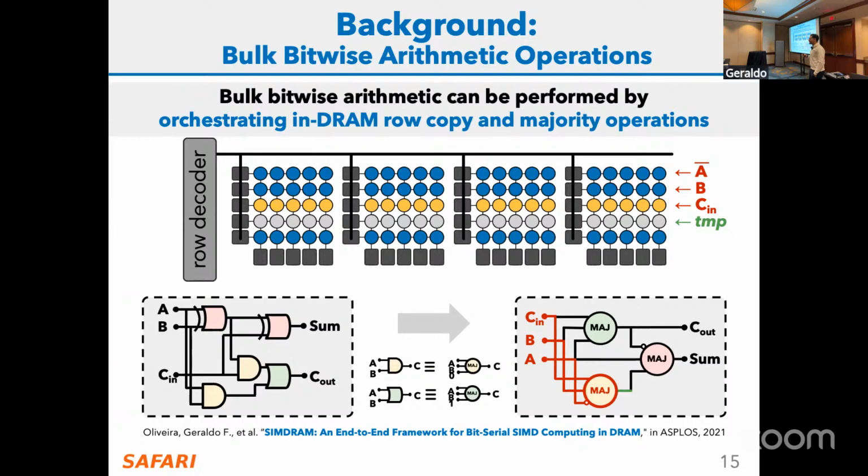This is for simulation base. So it's a repurpose, but in commodity DRAM, basically what we have is that inverted data is written. In DRAM we have one subarray. It's called an open-bitline architecture. So we have one subarray with a DRAM cell, the local sense amplifier, and then another subarray. Basically, neighboring subarrays share the same set of local sense amplifiers.